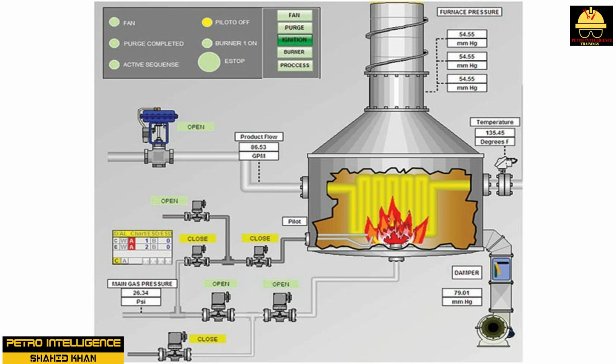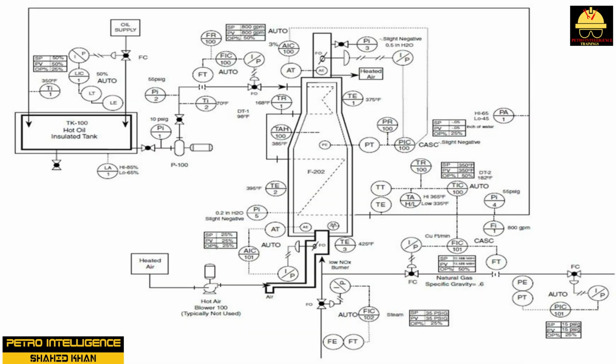Feed composition is best described as the composition of the fuel entering a furnace, which must remain uniform, or furnace operation will be affected. The charge composition must also remain uniform, or variations in process variables will occur. Fuel pressure control utilizes a pressure control loop located on the natural gas fuel line to the furnace that is designed to maintain constant pressure to the furnace burners.